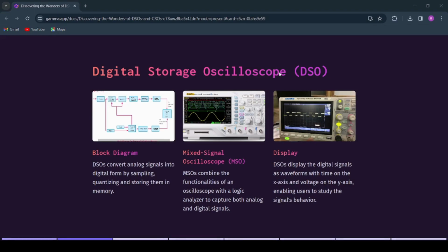The digital storage oscilloscope, known as a DSO, is an instrument which gives the storage of a digital waveform or the digital copy of the waveform. It allows us to store the signal of the waveform in the digital format and in the digital memory. Also, it allows us to do digital signal processing techniques over that signal. The maximum frequency measured on the DSO depends upon two things: first of all, the sampling rate of the scope, and secondly, the nature of the converter.